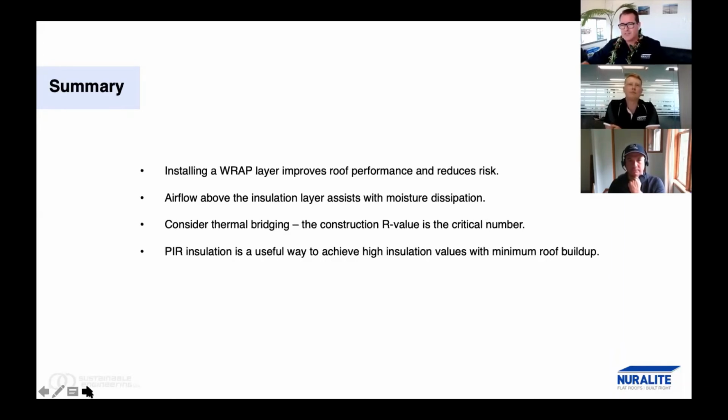I think even just a simple repaint of your roof, changing the color, can actually change the way your roof performs in a drying capacity. We've illustrated the airflow above the insulation layer is needed to get rid of that moisture. And also consider thermal bridging.